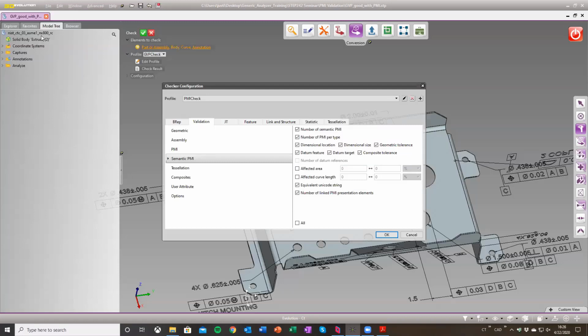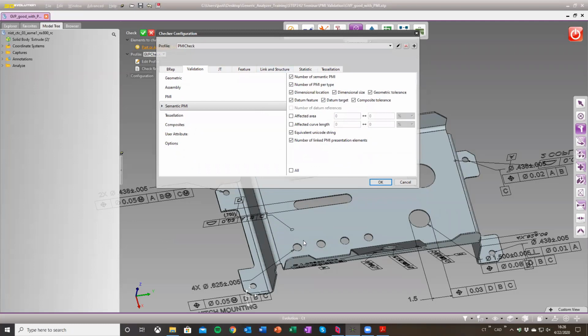So I do know that in a QIF format, if you're exporting to QIF and then bringing it up into another kind of software that does something similar, it is able to pick up the semantic difference. I'm thinking like hole or bolt patterns, right? So if you have 12 times or 4 times, and it's missing, say I dig on the annotation and only 11 of the 12 highlight, I'm not connected to 12 features, it should throw an error. That's the kind of check that I was looking for. If we're going to go down this validation road, and who wouldn't, because it's awesome, then those are the things that you need to look for.